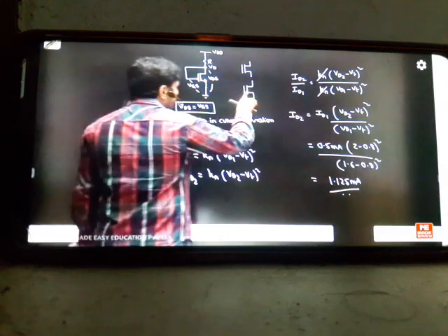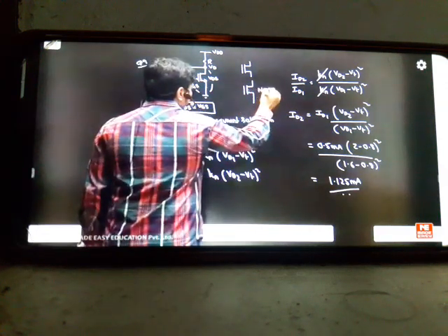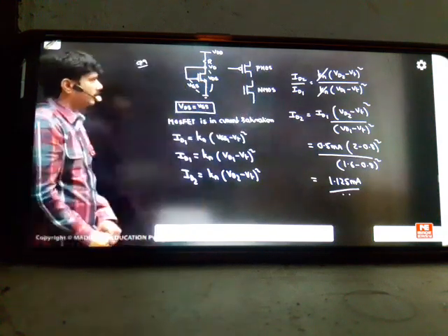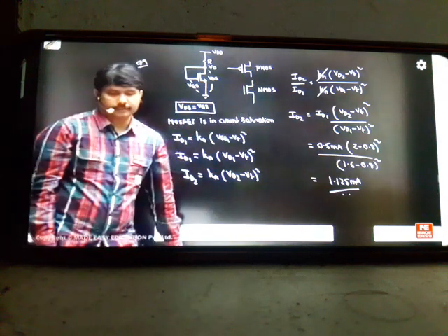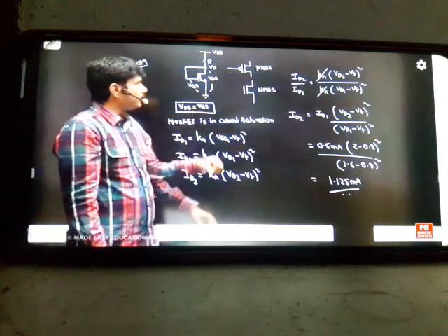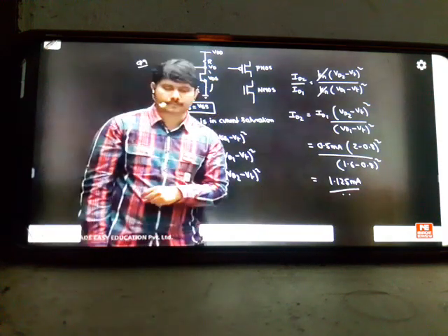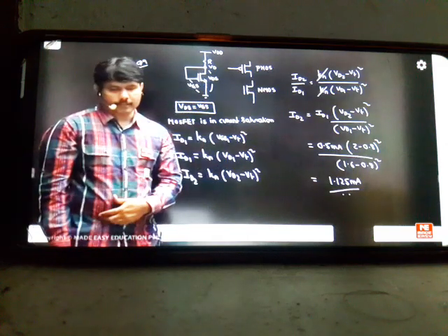But there's a trick here. This is considered to be NMOS. But if you want to show a PMOS, they'll keep a bubble here. This will become PMOS. So no arrows will be there, only in your digital IC designs. This is how the circuits will be shown to you. If there is a bubble at the front, we call it a PMOS circuit. If there is no bubble, it is shown normal, and it is an NMOS circuit. That is another way of representation, so don't get confused with this.